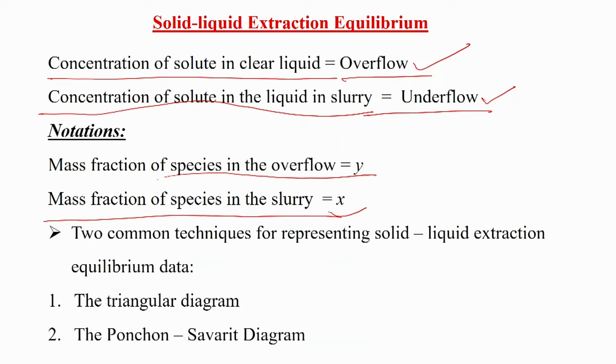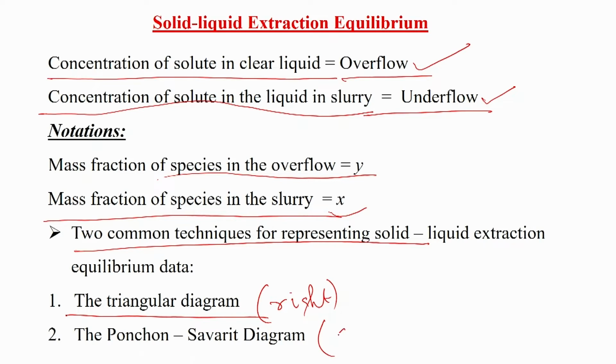Two common techniques for representing solid-liquid extraction equilibria data are the triangular diagram, and in most cases we will be using the right triangular diagram, and the Ponchon-Savarit diagram, which is on a solid-free basis. It is equivalent to the solvent-free basis in liquid-liquid equilibrium.